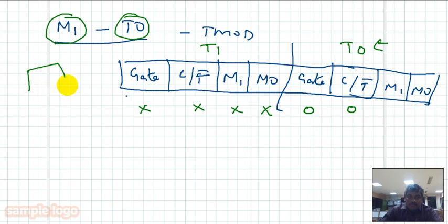So please remember, in 8051 microcontroller, you have only one hardware, and you can configure this hardware either as timer or counter by writing a value in the bits. And again, the last two bits M1 and M0 are used to decide the modes: 00 for mode 0, and we are going to use mode 1, so these two bit values are 0 1.